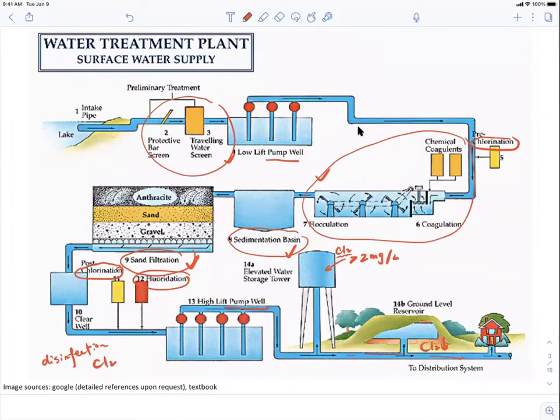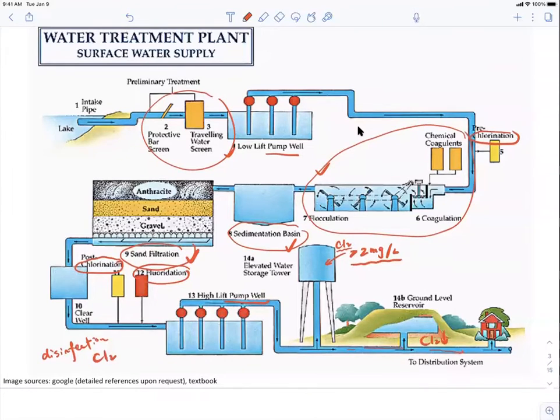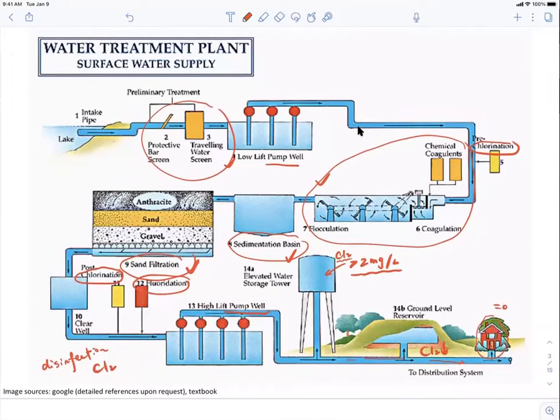So it might happen. And so if we don't have this overdose here, one thing that might happen is that the chlorine concentration, when it reaches the household, might drop down to 0. So if it's 0, then it doesn't have any function of disinfection anymore, right? So this is one thing that I want to point out regarding the disinfection.